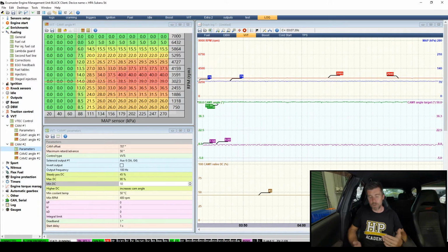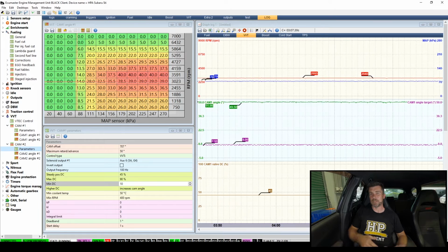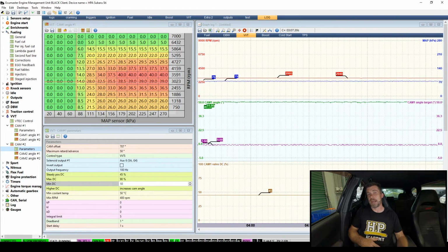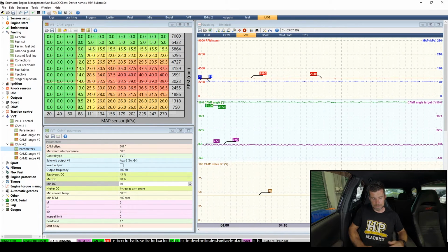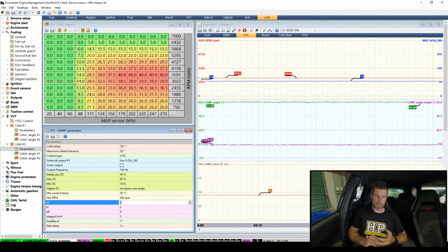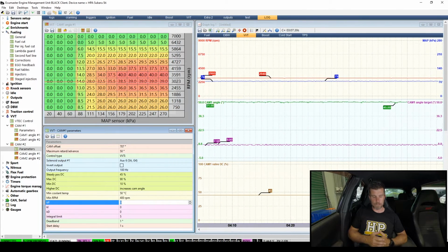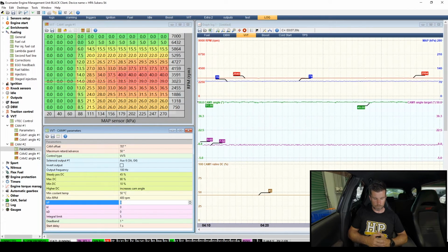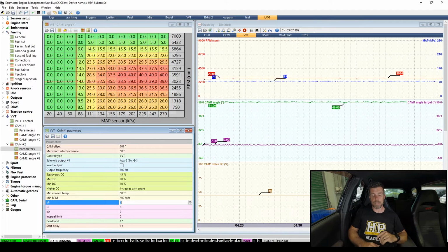And again, if we've got everything set up correctly and we're asking for sensible cam targets or changes in cam targets, we're not going to see the swing out to those extremes anyway. So we'll set those to 90% and 10% for the time being. Right, we'll come down to our KP, KI and KD. I already know that the sort of values we're likely to see for our proportional gain are somewhere in the region of maybe 25, 30 in this particular ECU.